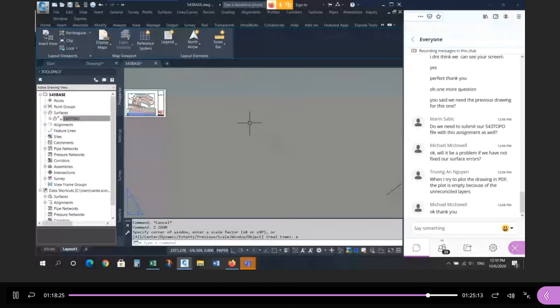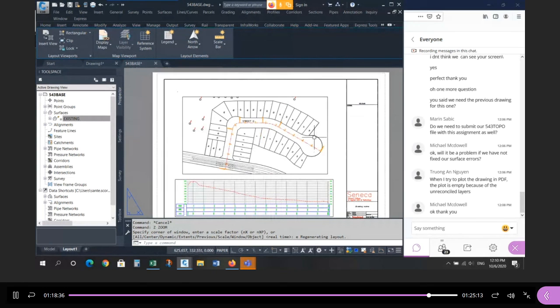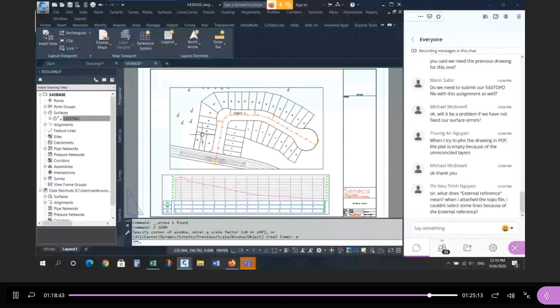So if you zoom extents and you see this effect, it could be on either side. You might have junk out here somewhere. Zoom extents. If you're not zooming extents and seeing this entire window, then you're going to have that problem. So zoom extents, and if there's space junk out here, delete it. Zoom in. If you see everything, then it should be fine.